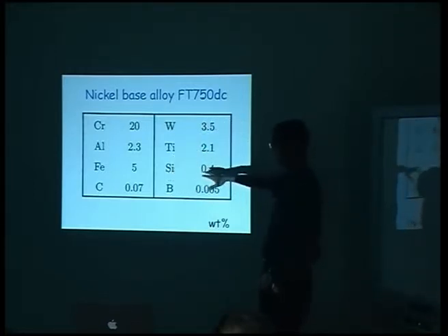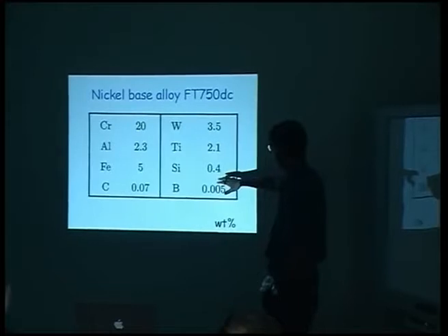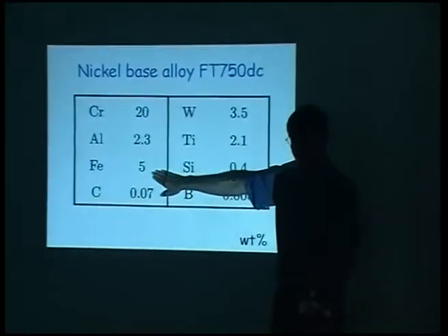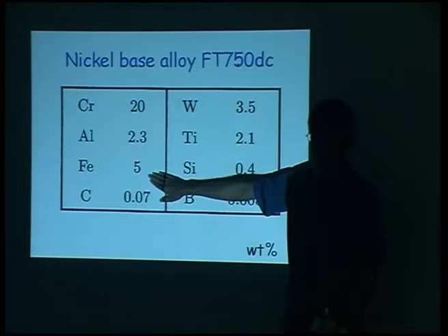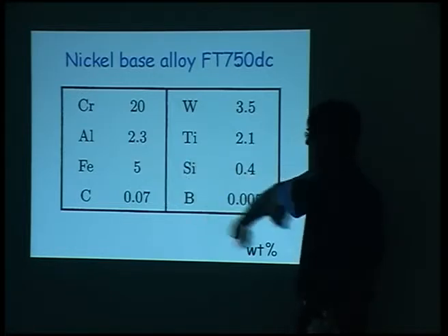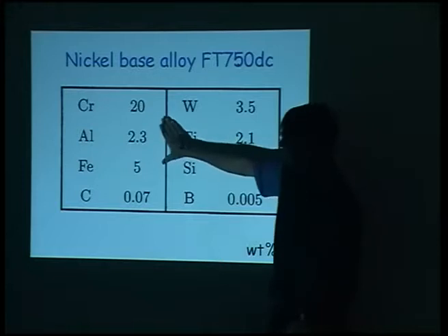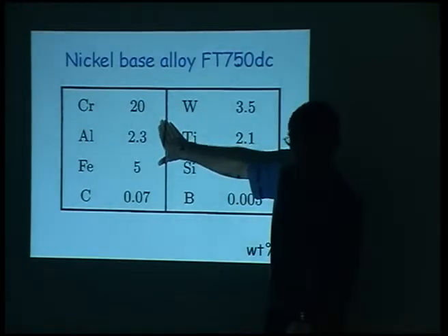And this was again in discussion with industry, because we don't really want iron in this alloy because it deteriorates the creep properties. But they said that if they can use scrap material to make the alloy, then it reduces the price enormously. So we've got iron because they would prefer to use ferrochrome instead of chrome.